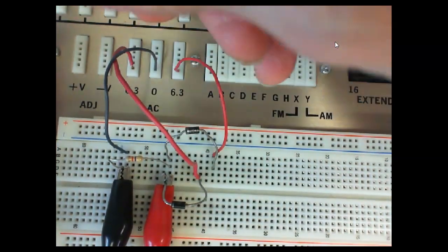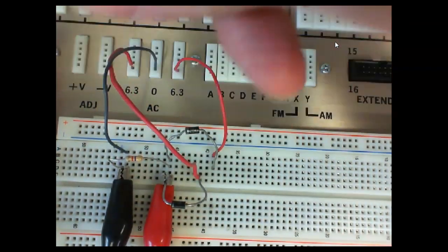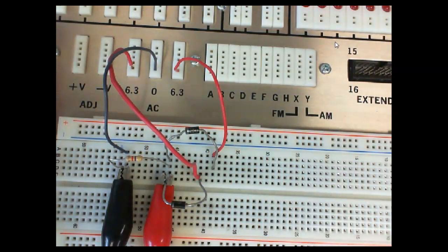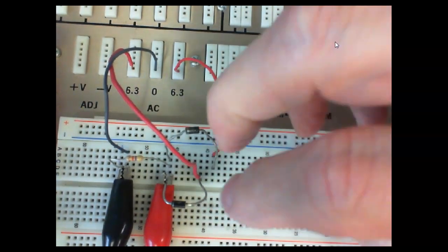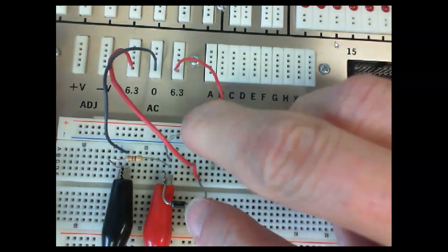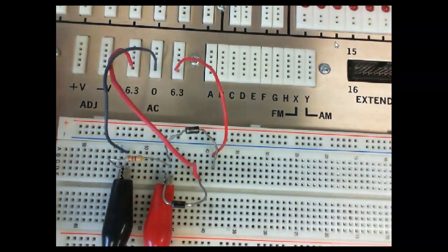I made it black, and then my two outside leads are red. So here's a circuit, real simple to hook up. Biggest problem we have here is people see the diodes in parallel, so they connect the anodes together. This is a positive power supply because the anodes are pointing toward the source. So we should expect our pulses to be positive.